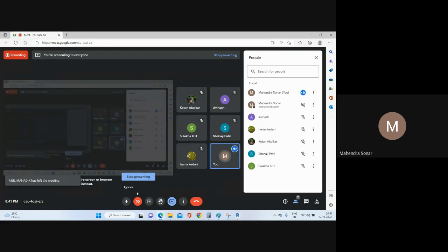When you need to add the stair, you should have two constraints. One is your base constraint and the other is the top constraint. On the basis of that you can calculate. Then after that you need to give your input for riser and tread, okay. On the basis of that they calculate, right?